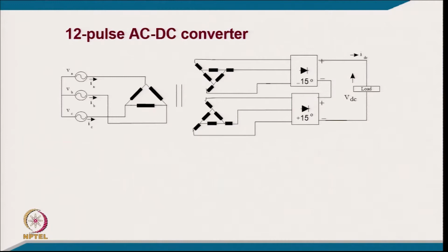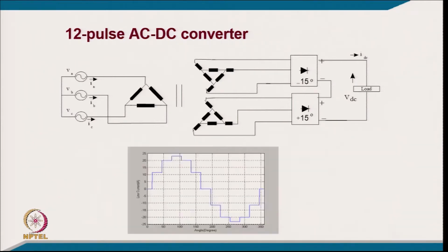So, here we are getting 15 degrees leading compared to the input voltage, and here we are getting 15 degrees lagging with respect to the input voltage because of the extended delta. So, the number of turns we calculate accordingly from the geometrical relation to get a phase shift, but you can still have the equal voltage, that is, their voltages will be on the same circle.